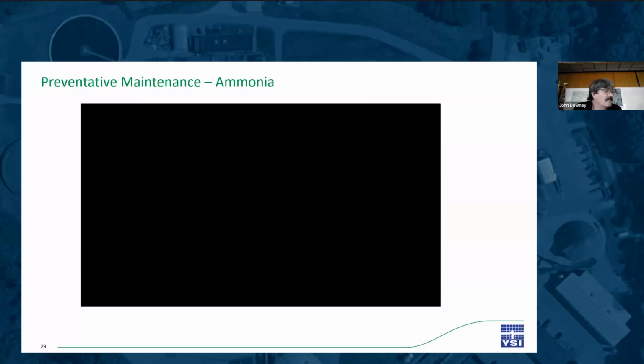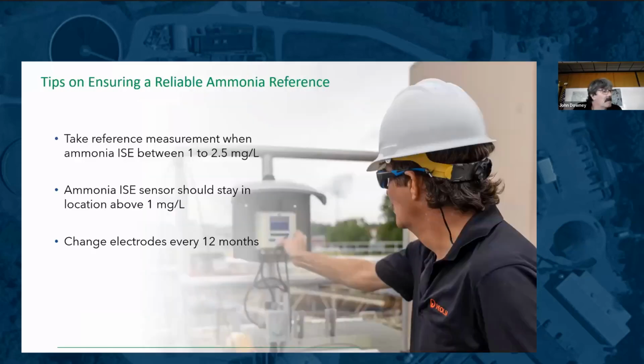Maybe we can visit that another time. We've determined that in the environment that we provide, an annual change of sensor faces keeps the networks running reliably. This means a 12-month service life for dissolved oxygen caps, for pH electrodes, and for the ISEs. Any of you who have this particular brand installed may have a different experience, but that's what we've found in 4 years of operation. It's been a pretty great experience, too.